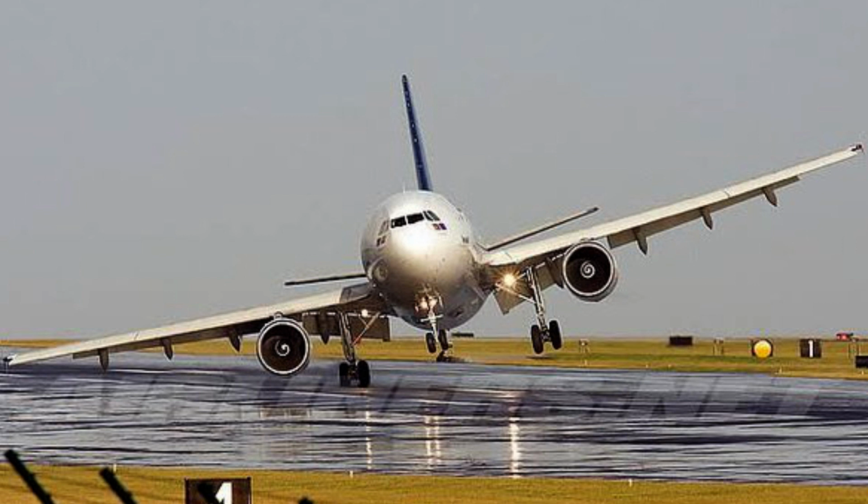Also, as the upwind wing rises, there is an increase in the AOA, which increases lift on the upwind wing, rolling the airplane downwind. When the effects of these two factors are great enough, the upwind wing may rise even though directional control is maintained.